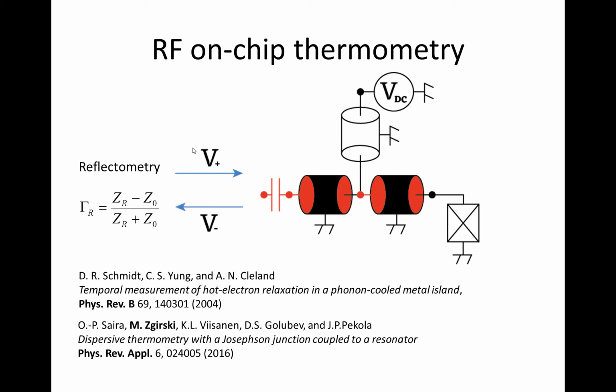The signal is being reflected due to the impedance mismatch, and the basis of thermometry in this case is that this reflection coefficient can be temperature dependent. So if I recall correctly, the bandwidth of such methods is of the order of 300 nanoseconds. So it could, in theory, catch the slower thermal processes, but this is not enough for tracking the faster ones.